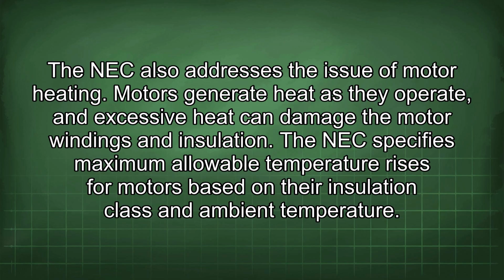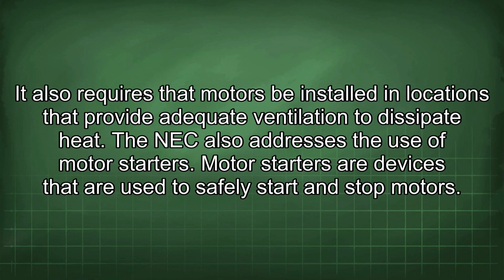The NEC also addresses the issue of motor heating. Motors generate heat as they operate, and excessive heat can damage the motor windings and insulation. The NEC specifies maximum allowable temperature rises for motors based on their insulation class and ambient temperature. It also requires that motors be installed in locations that provide adequate ventilation to dissipate heat.